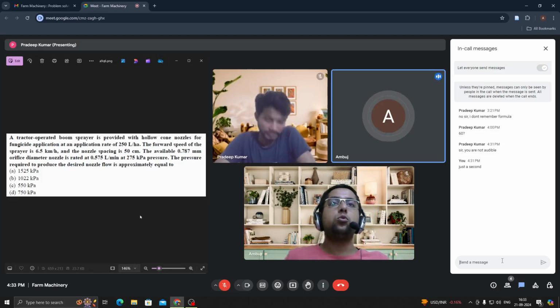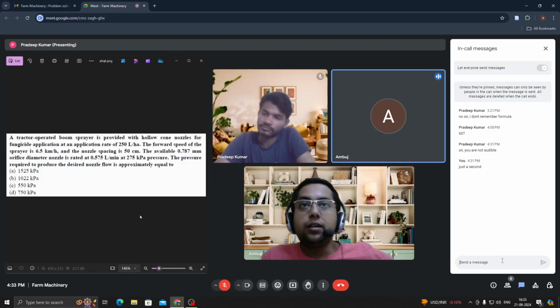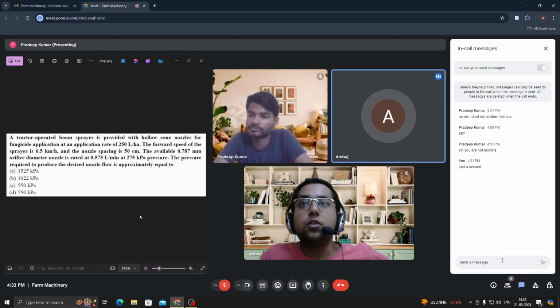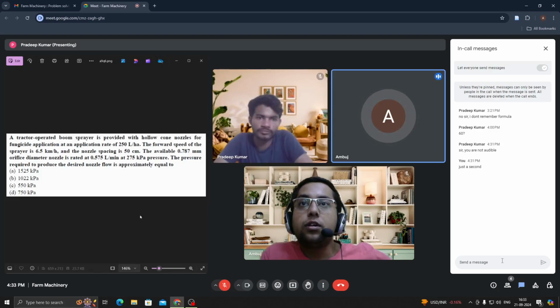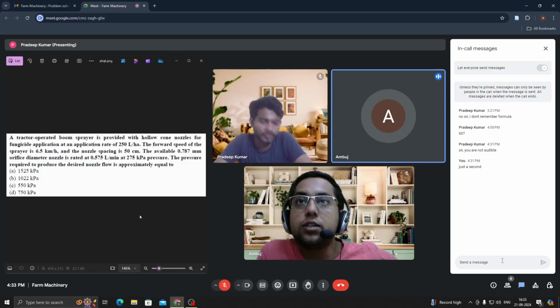Q is directly proportional to root over P, that I told you in this particular session only. You can see here Q1 they have given you 0.575 liters per minute. Then P1 they must have given you as 275 kilopascals. Now they have changed the conditions. Let us say it is P2, the pressure required for the desired nozzle.